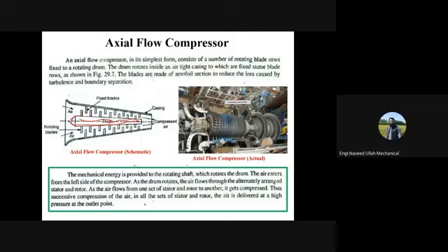As I told you, this is a drum upon which blades are mounted, and the combination of the drum and blades is known as the rotor, or rotary part, of the air compressor. We discussed earlier that there should be a runner or impeller or rotor. So this is that rotor, which imparts kinetic energy to the working fluid.